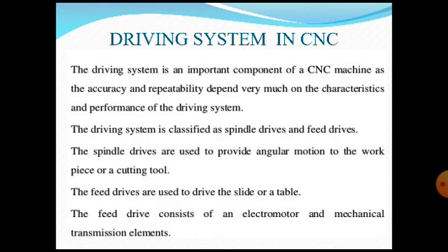In a lathe machine, whenever we hold the cylindrical workpiece in a headstock spindle, it is to be rotated, but there the rotation is manual, not perfectly accurate to the required RPM, because of various problems like slippage, losses and so many things. That should not be the case in CNC machines. That is why we are going to adopt servo motors or stepper motors.